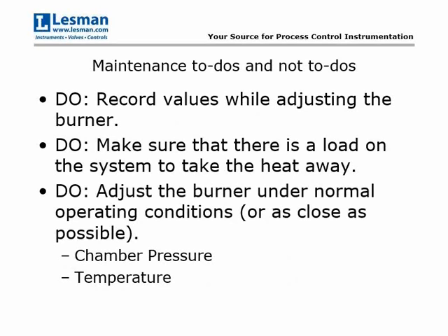Another do is that when you are making adjustments, you want to record values while making these adjustments, in case a condition changes after you set the burner up and the burner's not performing as well. You'll have a record of the values where you left off the last time that you set the burner up, to see if any of those have changed over time.